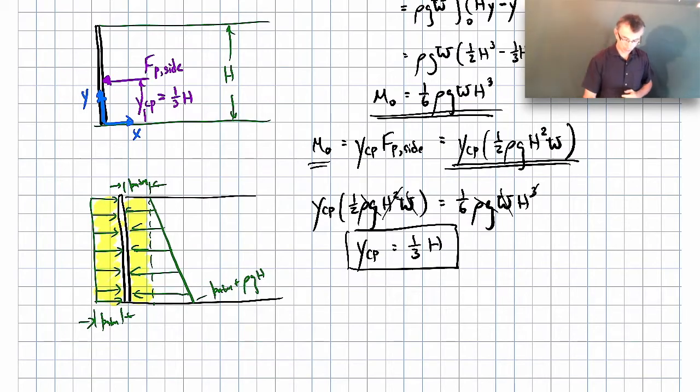So in the end, the only contribution you have to the net force acting on the wall is just this orange bit here, which is exactly what we dealt with when we were dealing with gauge pressures. So when you're calculating hydrostatic pressures, you can use absolute pressures if you want, but you don't have to. And it's really much easier to use gauge pressures instead. It just simplifies the calculation, because you have absolute pressure contributions on one side of the wall as well as on the other side of the wall. So it's just easier to do it in terms of gauge pressure.